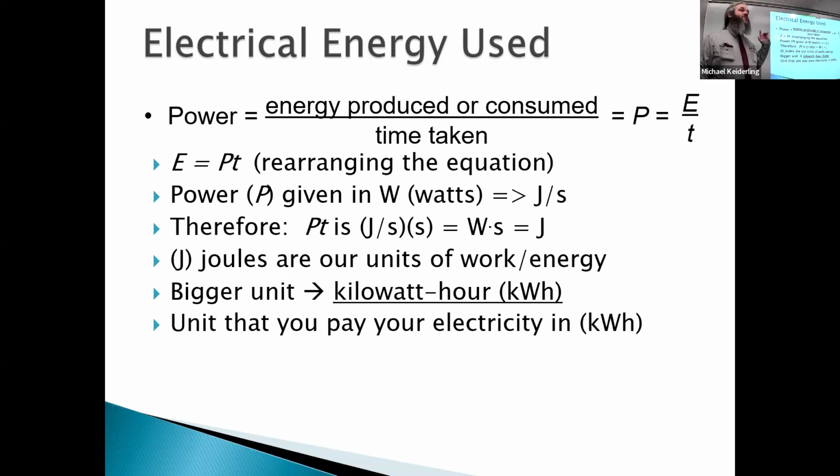Part of that was probably that it was easier to meter kilowatt hours early on, because you could set up something that moved at a rate proportional to power. Basically, the way that the electric meter works is that the speed it rotates at is determined by how much power you're using. And so how far it's gone is determined by how long it's been moving at that speed.